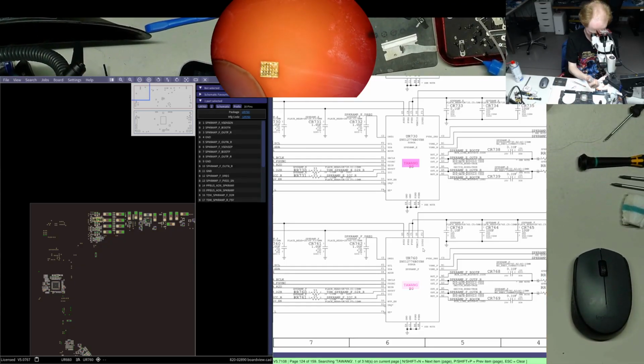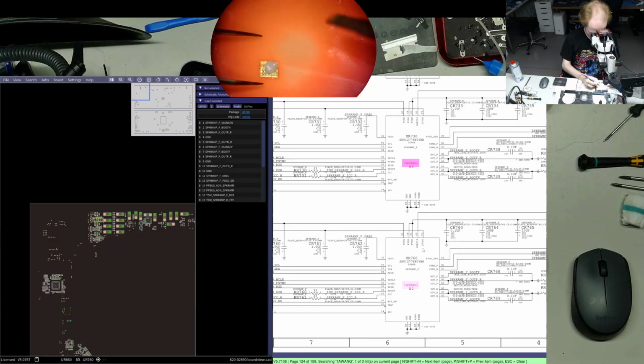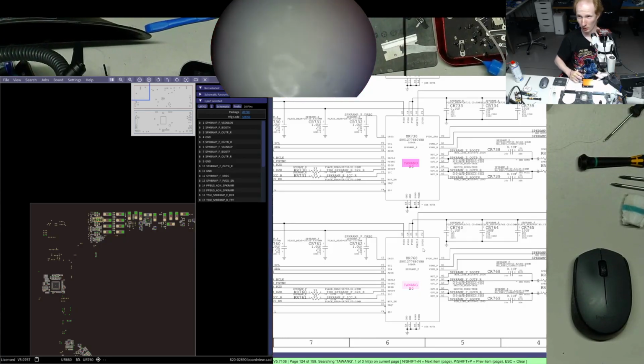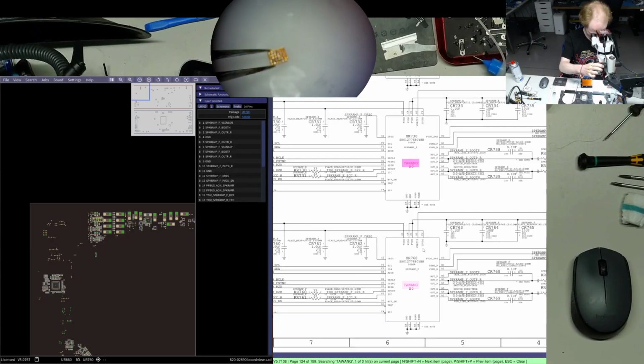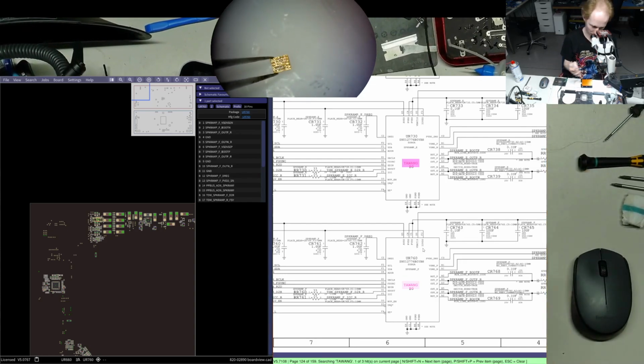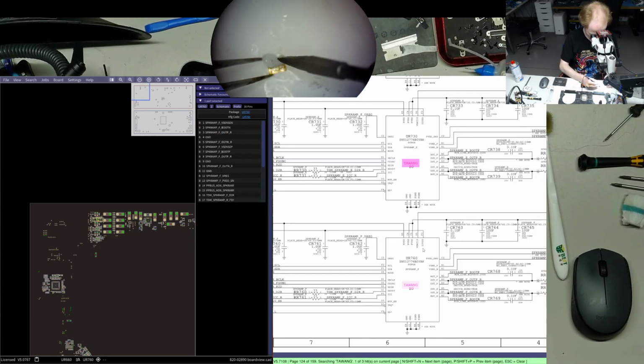Okay, I'm not very happy with how it looks. And by the way, never do the thing I did right now. Never solder a chip on the magnetic pad, because the magnet will attract the soldering iron, and unintentionally you will simply scratch it.